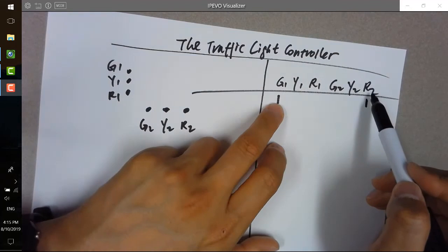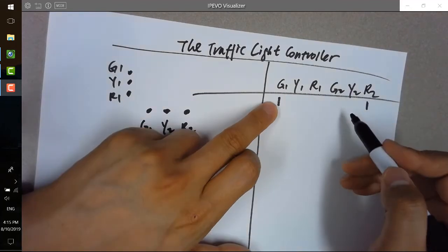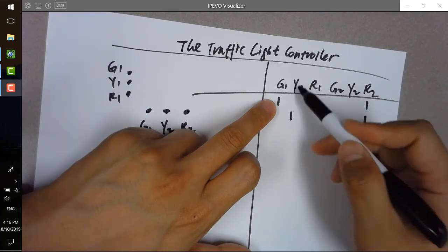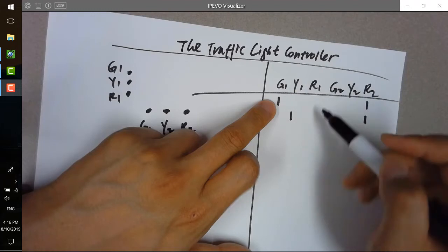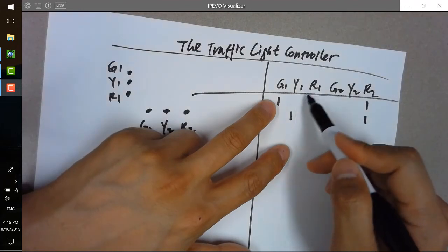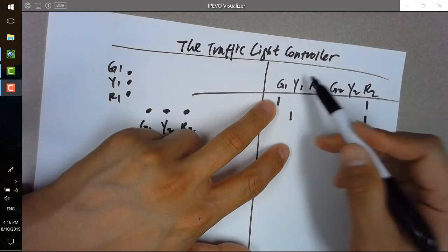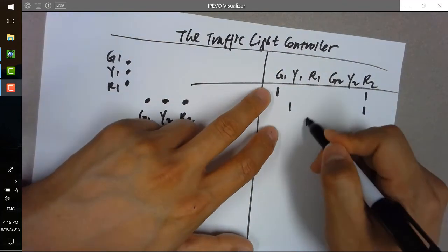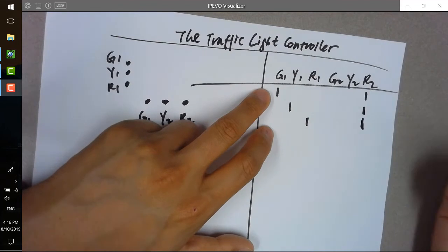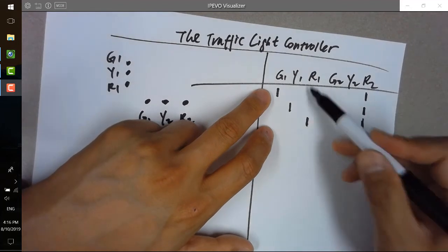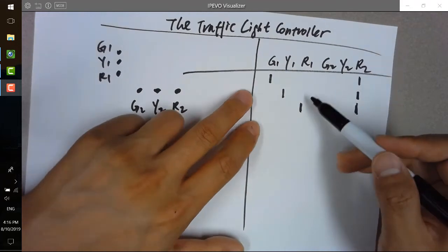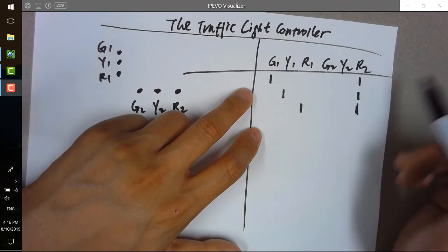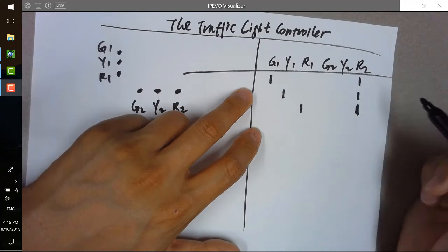Green and red at the beginning. The next step will be you want to change the green one to yellow and keep this one red. So you are giving a warning to the cars on that street saying a red light is coming, so please adjust the speed or be ready to brake. Next will be red and red. Before you give a green to the other street, you want to make sure the cars over here stop first, to be sure it's safe. So red and red will be pretty short sometimes, if you notice that when you are driving.